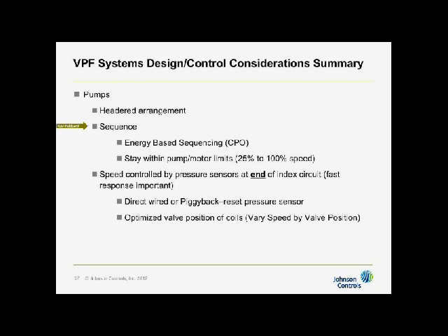Sequence these pumps using energy-based type sequencing because we are talking about doing high-efficiency plants. So you want energy-based sequencing that you'll learn in the next webinar. But we must stay within the pump and the motor limits. Don't go too slow with pumps because you may not be able to lubricate the bearings when you go below 25%. And when you go below 15 hertz, which is 25% of 60 if you're on 60 hertz, and of course it's a little higher percentage-wise if it's 50 hertz, going below 15 hertz on motors can quite often have the problem of eddy currents and overheating and so on. So we want to make sure that we stay within the pump's limits.